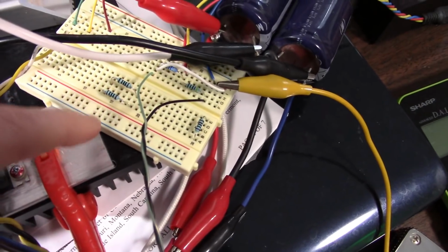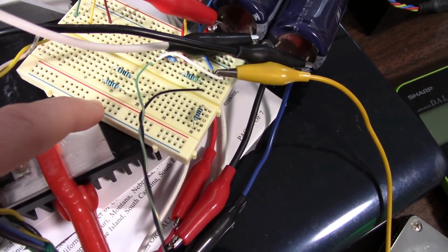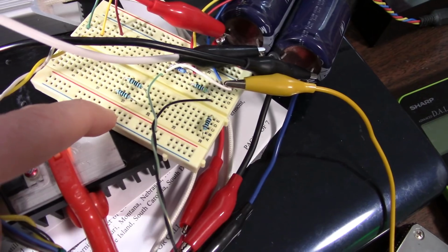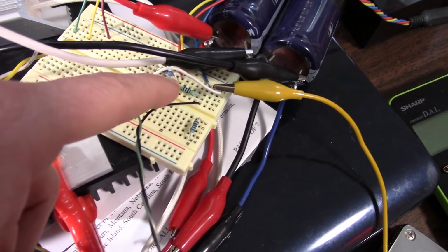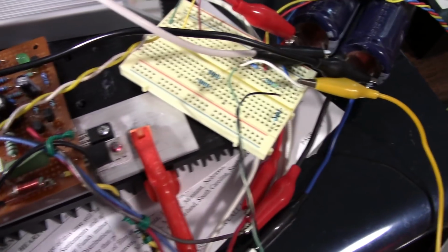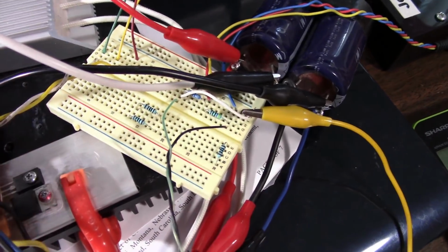We don't want that. And this board here, there's the attenuator. I did make a mistake. The 100 ohm and 1K resistor is a little bit too low a value. Those would overheat when I'm driving the amp hard, so I went up to a 470 and 4.7K. See how that works.